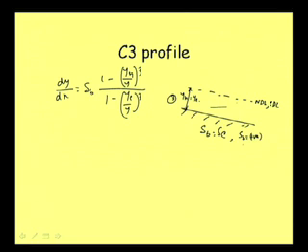For any of this critical condition flow we have NDL equal to CDL. That is why these two values will be identical, numerator and denominator. So, this ratio will always be equal to 1, and dy dx is equal to S0, and of course it is positive.